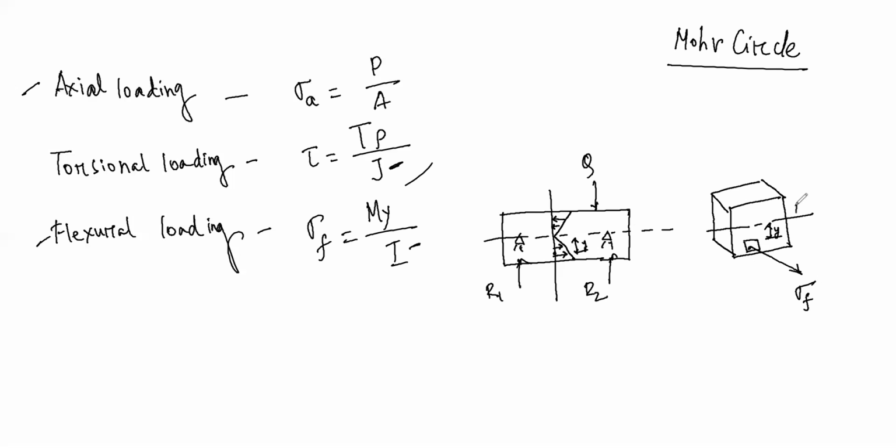If I take the section mn, at any point at distance y from the neutral axis, the stress is working perpendicular to the surface. So this is flexural loading, flexural stress.